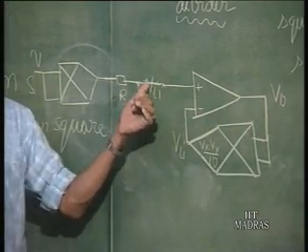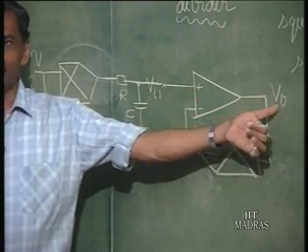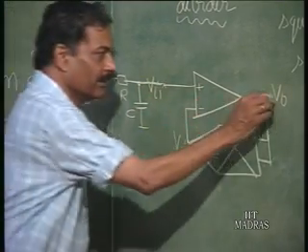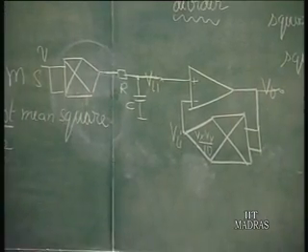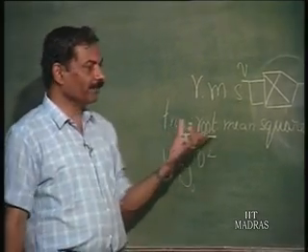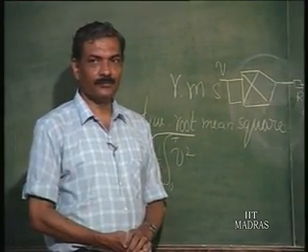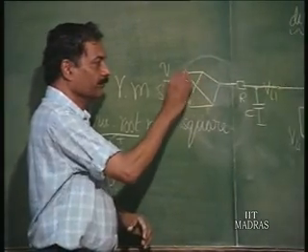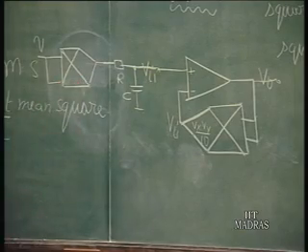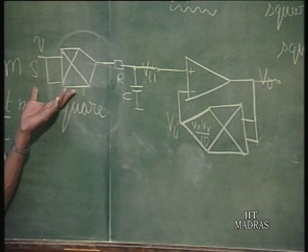This averaging gives a DC, so you will now take the square root of that. This complete circuit is nothing but a very useful tool called a true RMS, root mean squared, indicator. The entire thing can be built using multipliers. Such units are available in the market for finding the true RMS value of a given waveform.